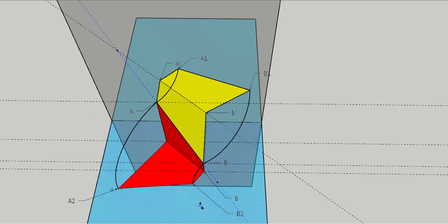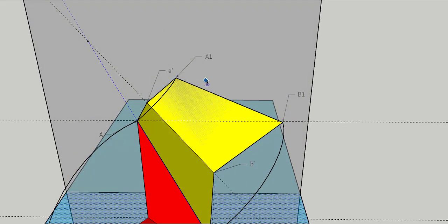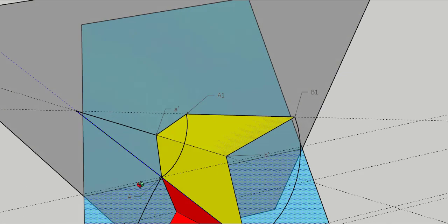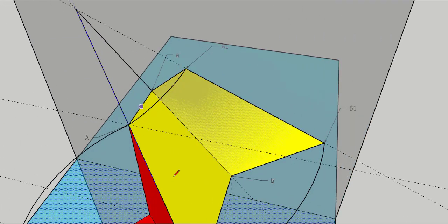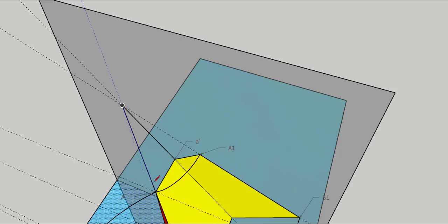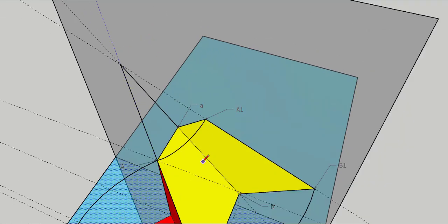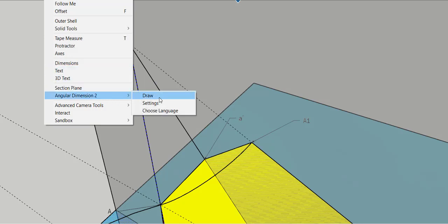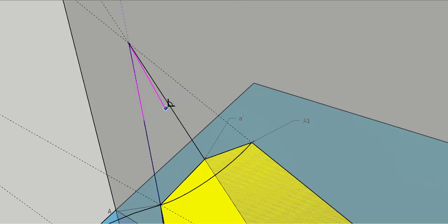Okay, I've drawn that, and then again I am extending this. So if I'm drawing a line through these guidelines here, this capital AB has been extended towards the vertical plane, and I have also extended the line A dash B dash. And if I measure this angle here, I get approximately 27.1 degrees.